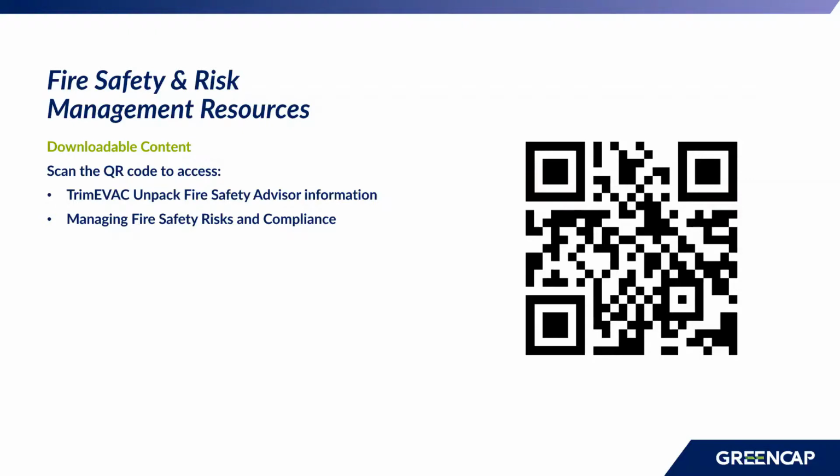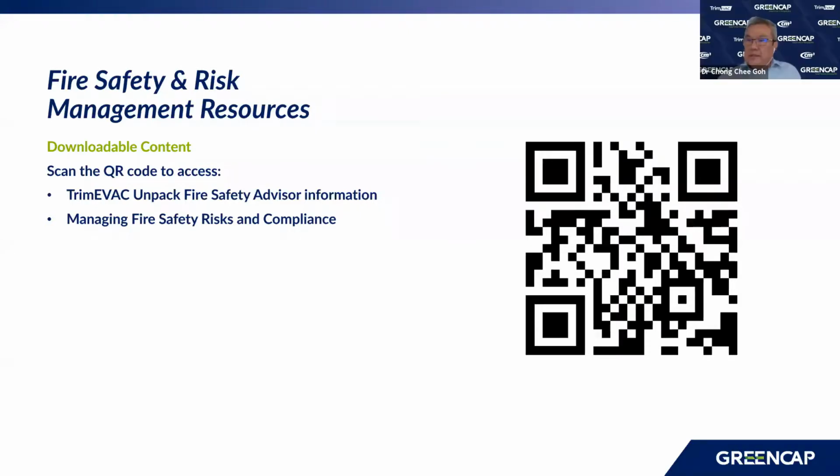Sorry, again muted. Annual fire statements. What type of premises must complete these or have them prepared? That's from James. I think in most jurisdictions and most states, the regulation calls for class 2 buildings to class 9, which are your common office buildings, retail, industrial buildings, healthcare, individual dwellings like our home. We do not need to complete an annual declaration. But hotels, if the use of the building is for transient, various types of occupants, yes, you do need to have annual safety certification every year.